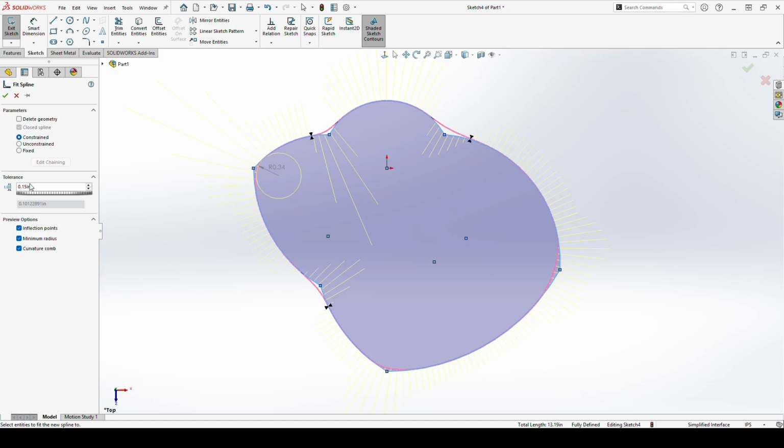Last piece that I wanted to talk about is this down here. Basically what's happening is all of these yellow lines, you saw me click out of it, are just a visual representation of how sharp the curves are at any given point. It's just a curvature display. It lets you see a little bit more clearly how quickly we are changing directions for our lines.